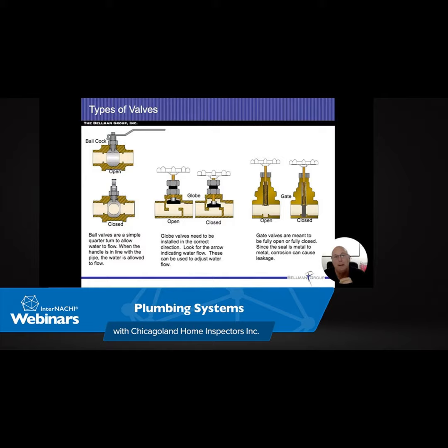So, how do we prevent cross connections? The best prevention is going to be with an air gap. All right, so some sort of an opening. If I fill up that funnel with water and I just keep filling it up, that funnel is going to overflow. There's no way that water is going to get high enough so that the pipe that's above it is going to be in the water, and then I'll be able to siphon from there. So any sort of an air gap will always be our best defense against any sort of cross connections or siphoning of our water system coming in there.